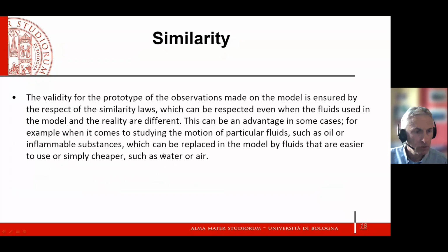Okay, now, basically, what is the conclusion of the reasoning so far? The conclusion is that if we are interested in describing both sediment dynamics and sediment transport, we need 9 plus 2, 11 physical quantities, and we need 3 fundamental quantities, and we have to make sure to preserve 8 dimensionless numbers, which we listed, we made a list.